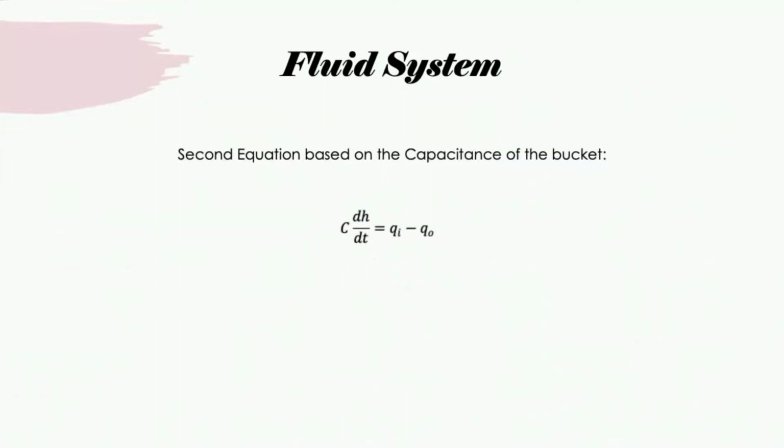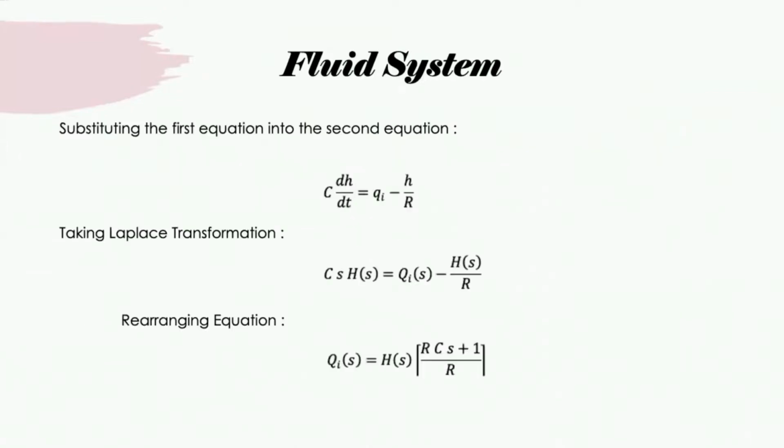The second equation is modeled after the capacitance of the bucket. By substituting equation 1 into equation 2 and taking Laplace, then rearranging the equation, the following equation was formed. This will be referred to as the final fluid system equation.